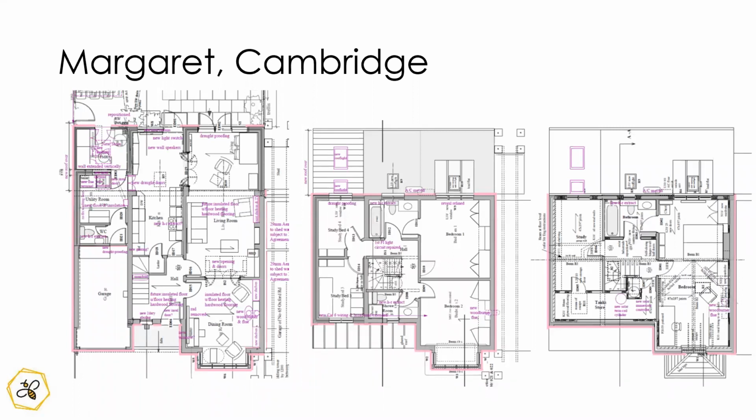Okay. And I don't know what type of underfloor heating you've got, but some of it will only run up to 40 degrees. So you set your heat pump at 40, not to go above. That's what I understood, 35. Yeah.